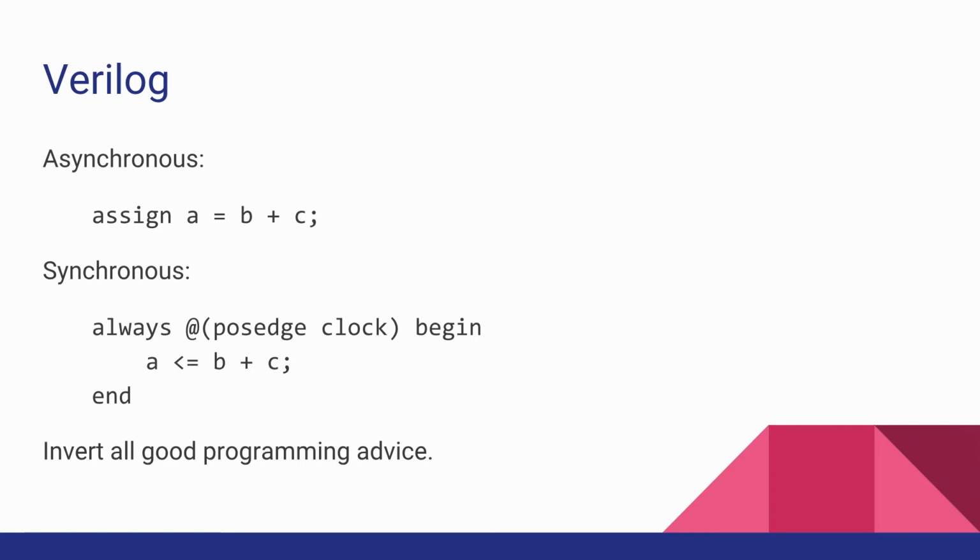There's this one adder, and it routes those 2 numbers through the one adder, and it gets the output and writes it back to A. In Verilog, that's not what it means. What it means in Verilog is make a physical adder, like that's permanently there all the time. Get whatever B is, which is let's say an 8-bit register. Get whatever C is, route them to the adder, and then whatever the output is, call that A. And that's what that means. So it's adding all the time, nonstop. And if you change B, as fast as those signals can propagate through the FPGA and get through this adder,